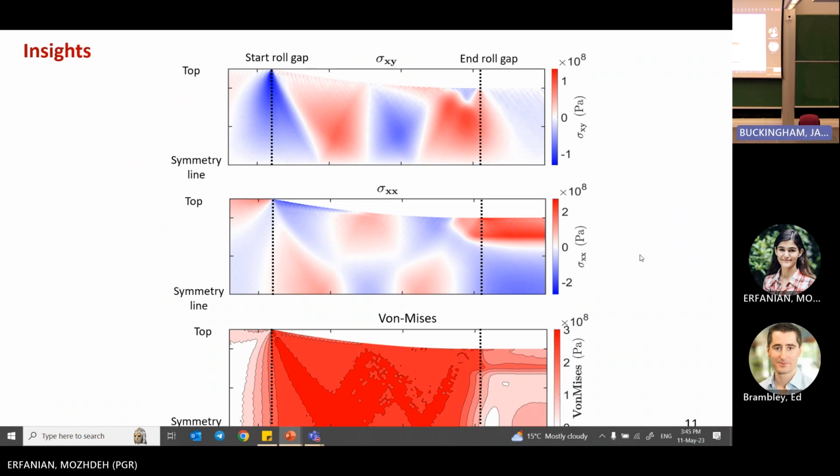And the other unknown I said is residual stress, and residual stress is actually the stress that remains after the process. And you can see the location where the exit wave leaves the roll gap can show a huge amount of residual stress. So again, all of these are hypotheses, but it seems this oscillatory pattern is linked to these kinds of unknowns.